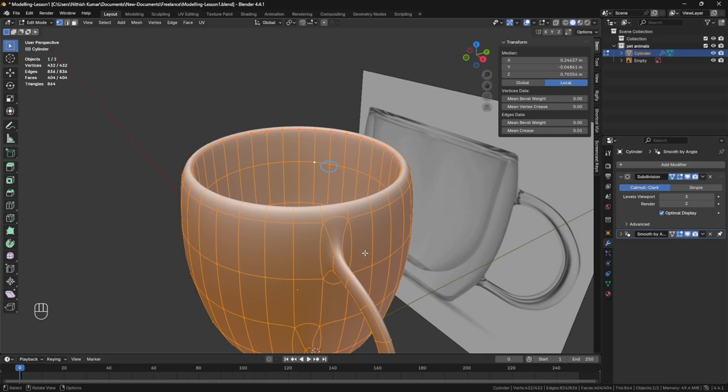So for a room or for a scene, it depends on the quality. The higher the quality, the higher the polygons. For medium quality, medium polygons. But the ideal solution would be to achieve higher quality with medium or low polygons. That's why we use edge crease, edge bevels, and all those things, so that we don't need extra loop cuts.